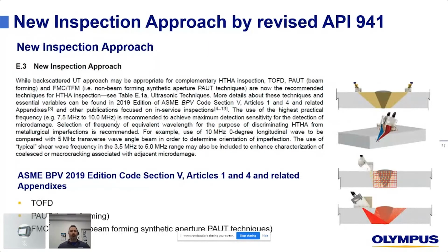New inspection approach. We have different methods that were added to the Article 1 and 4 appendixes: TOFD, time of flight diffraction, phased array, whether it's pitch-catch as represented here or pulse echo as represented below, and FMC TFM, another method that more and more people are getting familiar with. We'll go over the basic ABCs of these methods in future slides.